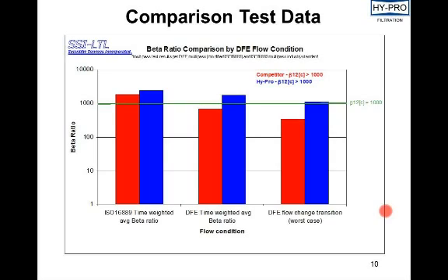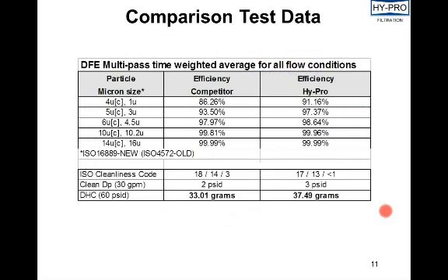But again, the idea of DFE is we're making a filter element that's used in a stressful environment, and we want to test it in that same environment so that we can predict the performance in the field. It's a lot like buying an off-road vehicle and you only tested it on the highway when you use the antiquated ISO 16889 standard. So we want to test these filters in the way they're really used so we know what kind of cleanliness we will be delivering under any circumstances.